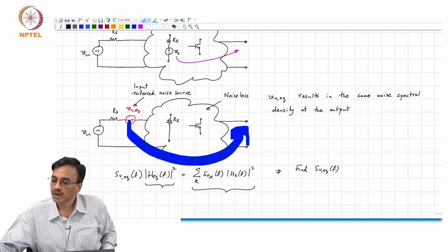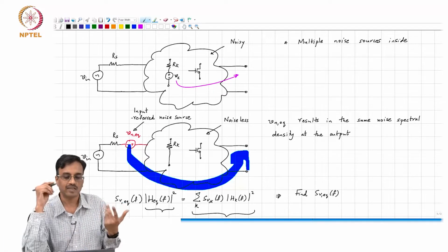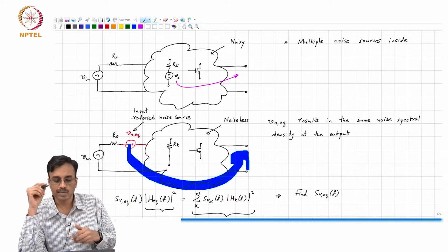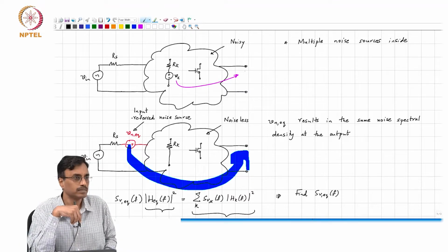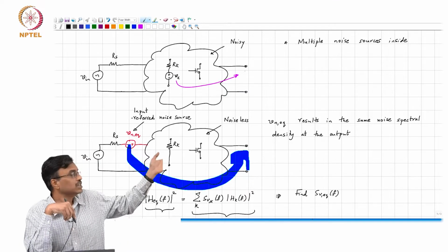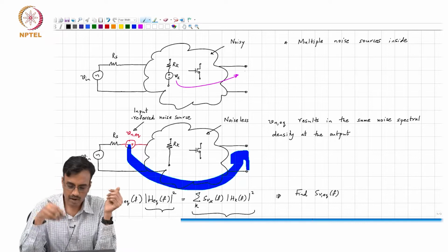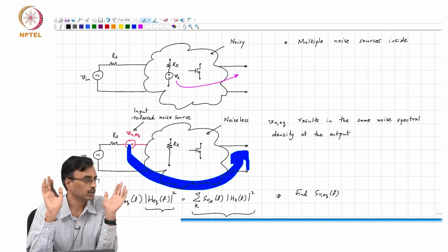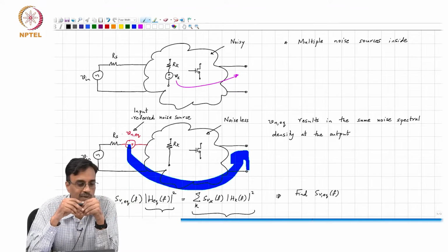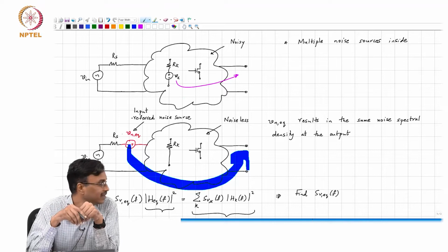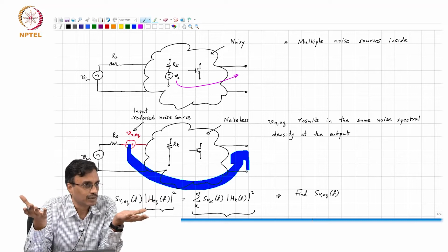All right. So, now let us get started. Couple of things that I would like to draw your attention to. One is our job therefore seems to be to find the transfer functions from each of those input sources to the output, and also from Vn equivalent to the output. Given a general network, we can only come up with some broad guidelines. Without knowing the network, it's evidently not possible to come up with the transfer function, correct.